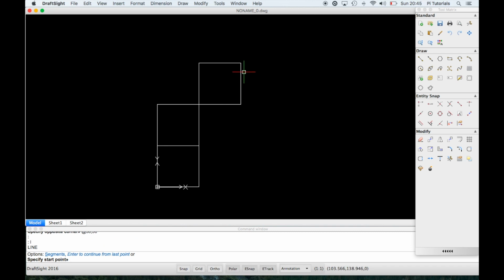So I can draw a line at, so I'm going to draw a 45-degree line, 50, 50 again, and say I want to come down here 100 millimeters, so that would be 0 in the X direction. And let's do at 0, and then minus 100, I want to come down, space, I'm just drawing it to there. And then you can mix and match, so I can still click.